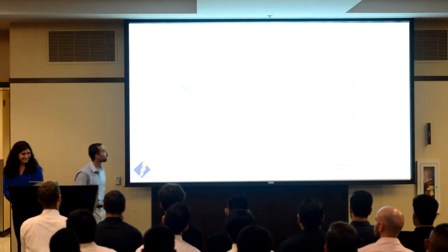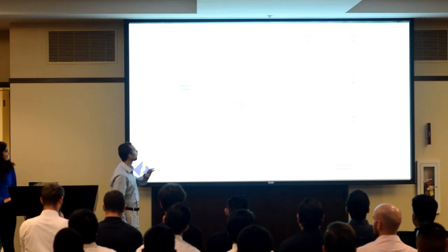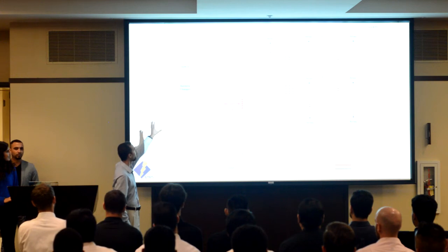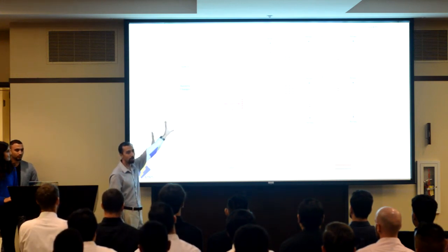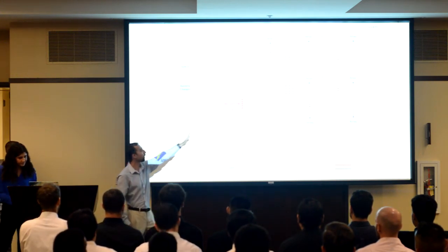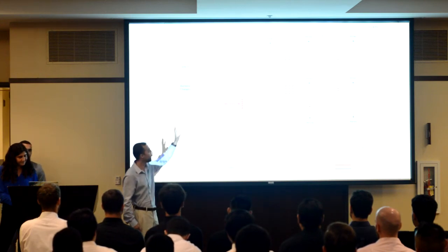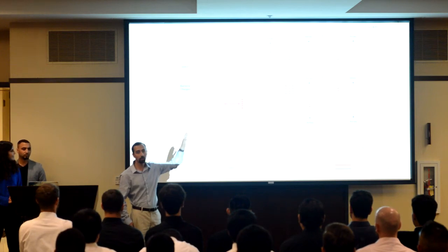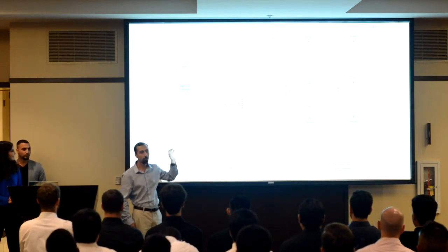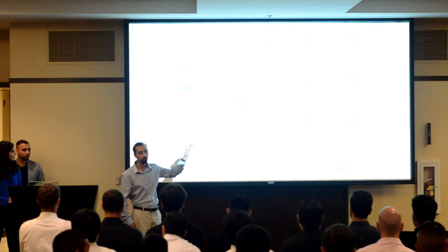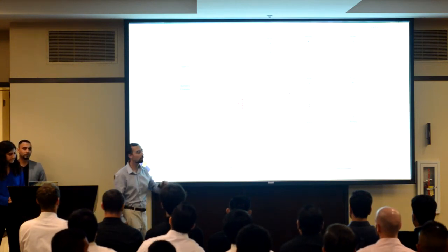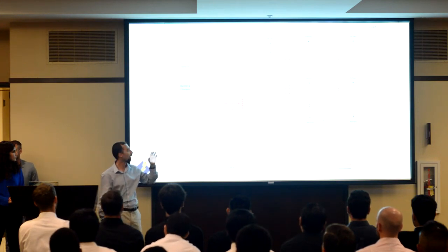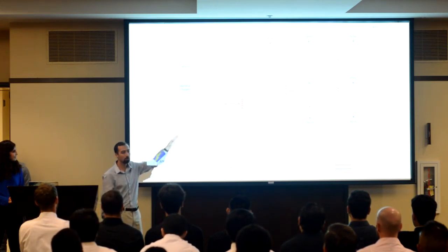So to tie it all together and to give you the overview again, the main components of the system are the battery, the 2 inverters, a pure sine wave and modified sine wave, and 3 plug-in loads. We have multiple relays. We have a relay to select between inverters. We have relays on each of the loads to turn on and off the loads. And we have relays to select between filtering and non-filtering. We have multiple sensors. We have main voltage and current sensors. Each of the loads has a sensor for currents.